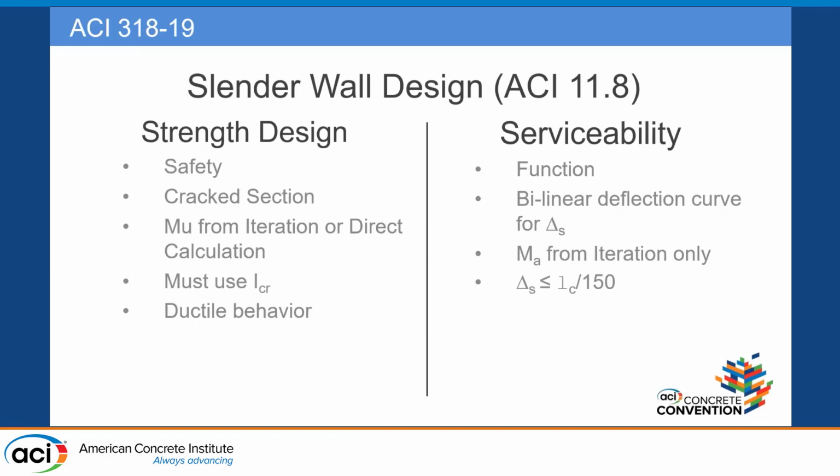A lot of what John presented and showed you is on the serviceability side and predicting how that panel is going to deflect, looking at, you're going to get some permanent deformations if you get too much of it. What I want to look at and really focus on more here is going to be the strength side of that equation. As designers of panels and buildings, our first responsibility is to make sure that we have a safe structure. And then we can worry about serviceability.